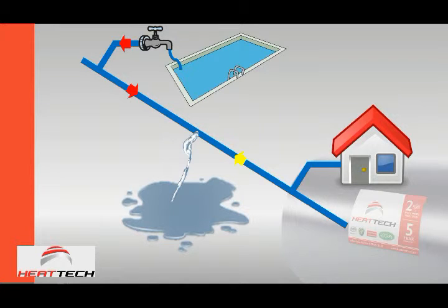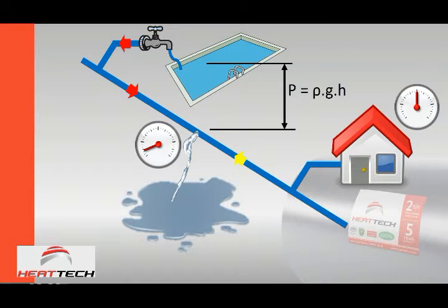Because as we've explained previously, there must always be a balance of energy. Energy cannot disappear. So now suddenly you have water running out of the line. There's a velocity. It causes a drop in the pressure. Let me just get that image up, and that explains it. It causes a pressure drop at the point where the water leaks, which means now water will flow in that direction. It means water out of the household might flow towards the leak. Water in the main line might flow that way.